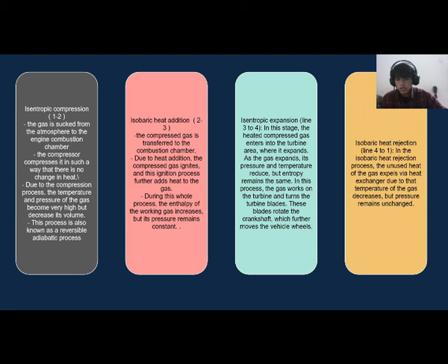Isobaric heat addition, 2-3. The compressed gas is transferred to the combustion chamber. Due to the heat addition, the compressed gas ignites and this ignition process further adds heat to the gas. During this whole process, the enthalpy of the working gas increases but its pressure remains constant.